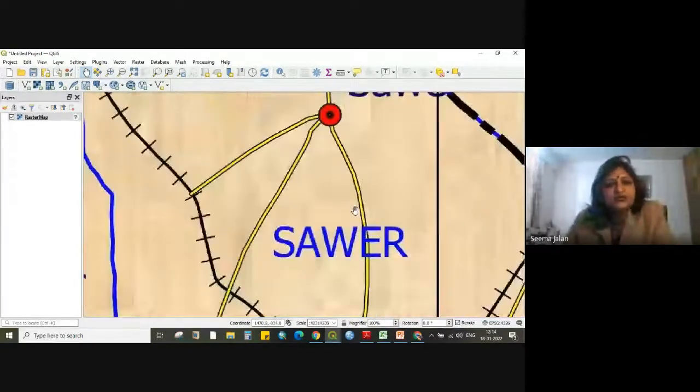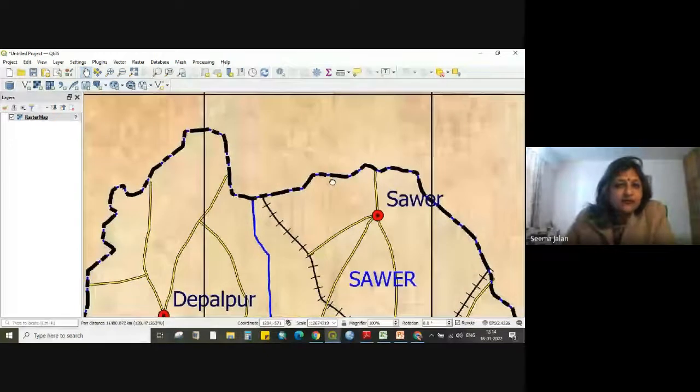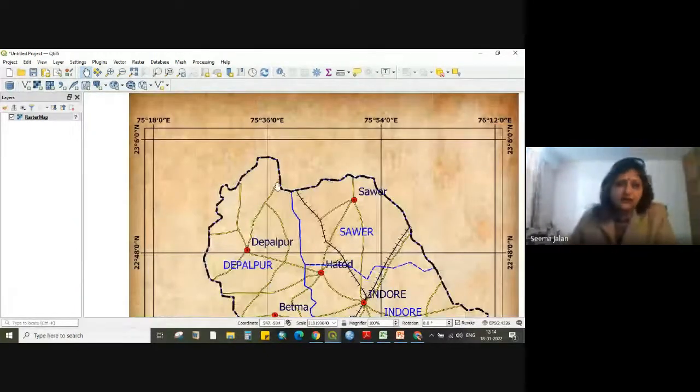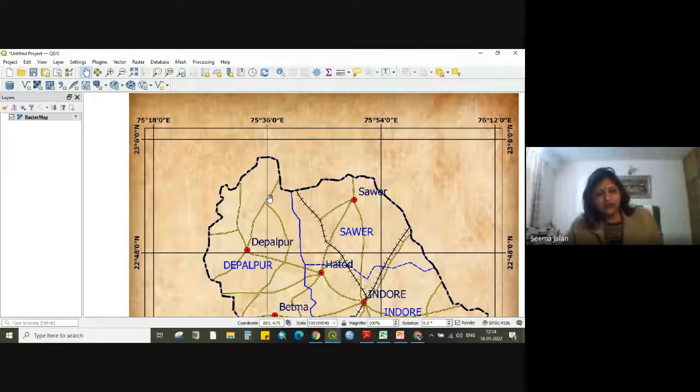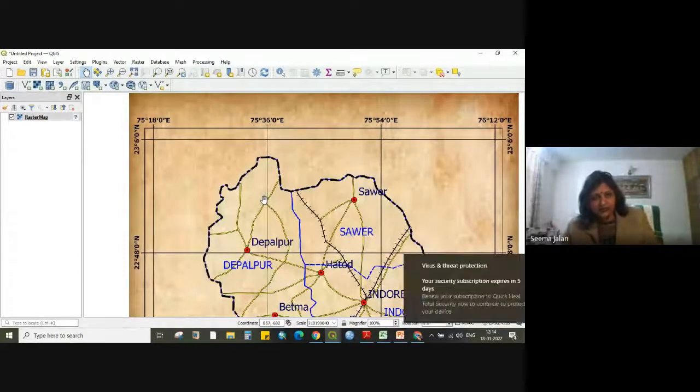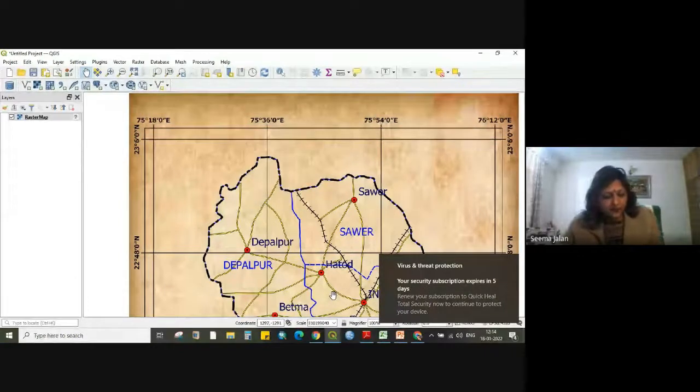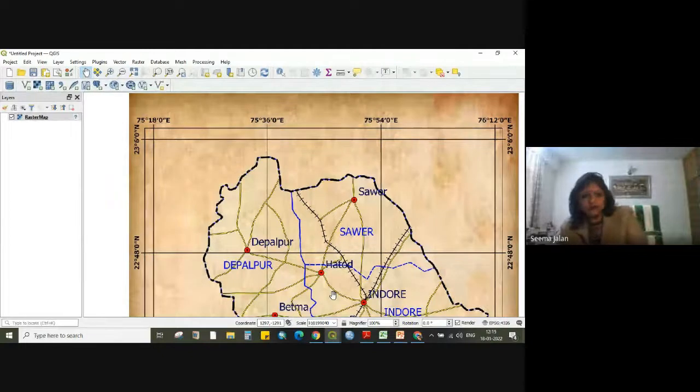Georeferencing is a two-stage process. First, you project the mesh, then you fill in the pixel values. So first, you have an input grid. You use your mathematical model, whatever transformation equation you have designed, and using that equation for every input image coordinate, you calculate a map coordinate. So you have an output grid.